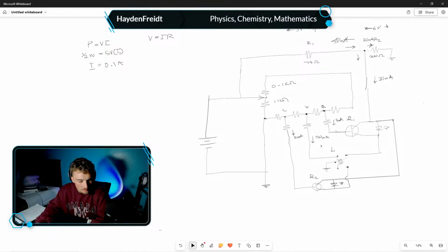Shit, I think I just found a problem with the circuit. I just found a big problem. Even 100 ohms only gives me 90 milliamps with 9 volts across it, and I'm not even going to have 9 volts. It's not going to happen. Ah, shit.